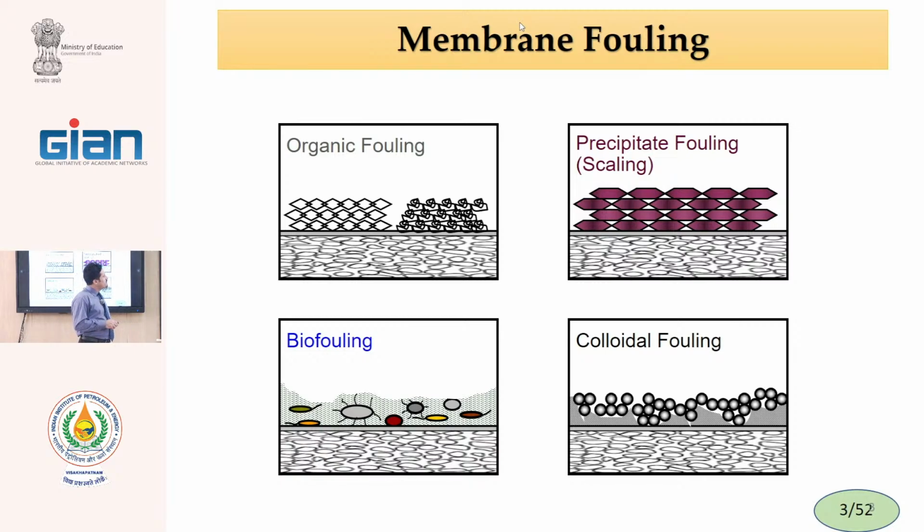In this case, we have a sedimentation of saturated components with increasing concentration of the salts on the surface of the membrane. On reaching the saturation point, the extra salts that cannot be dissolved in the saturated solution will precipitate and cause a new layer on the membrane surface.